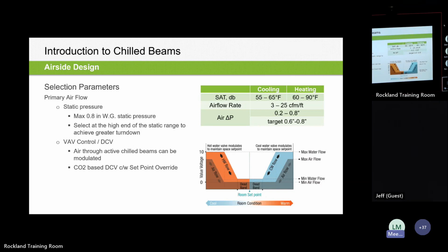So the CFM difference from that would be roughly 50%, I think, in most nozzle sizes, going from 0.8 inches of water to 0.2 inches of water.